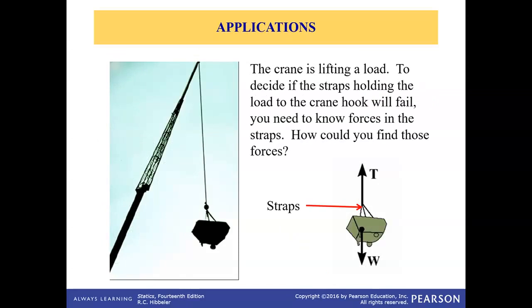Let's look at a few applications of equations of equilibrium. So the crane is lifting a load. To decide if the straps holding the load to the crane hook will fail, you need to know the forces in the straps. How would you find those forces? And the answer is to draw a free body diagram and apply equations of equilibrium.